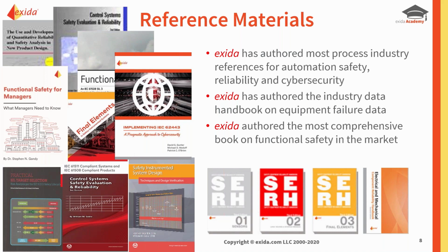So they're there. The other thing that we provide is our SAEL, the Safe Automation Equipment List. If you look at the website homepage in the top right-hand corner, you'll see the SAEL. That basically gives you a list of certified devices. So if you're a SIF designer and you're looking for a specific certified device, then you can go in there and see if there's one for a specific manufacturer that you had in mind, or if not, there might be another manufacturer's device that you can use. And you can access the certificate from the website, and if we're allowed to publish it, you can also access the assessment report, which says how we came up with the failure rate numbers.